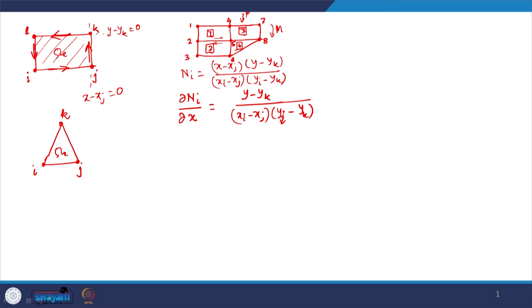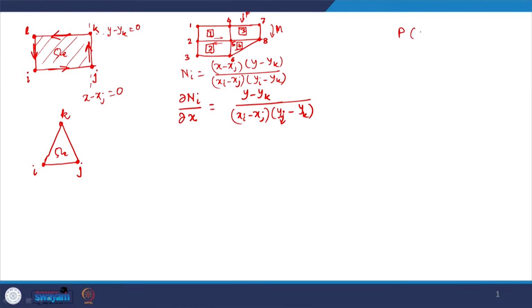So, point load P can be easily modeled as a Dirac delta function, that is a discontinuity. So, point load P at x equal to x bar can be represented as function P of x as P delta x minus x bar, and then this function P of x can be treated as a continuous function of x and substituted in the integral.